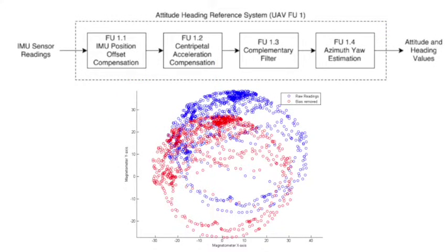So then the magnetometer is used to measure the heading of the aircraft. I decided to take the route of using the magnetometer because integrating the gyro wasn't such a great idea because of the gyro drift, and then the accelerometer doesn't help, so you can't use a complementary filter because you don't have any other reference. So I decided to use the magnetometer, but it also had a few problems.